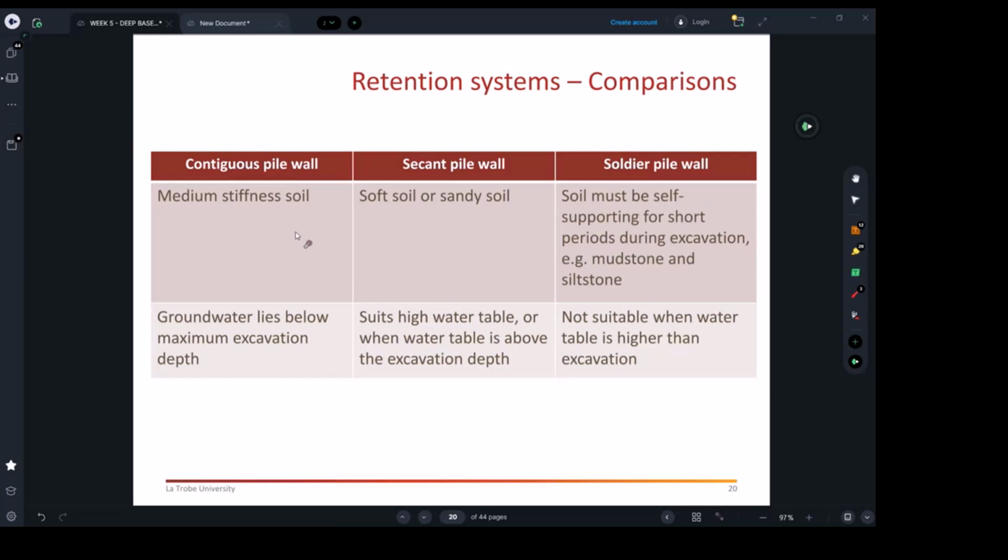Remember, when the soil engineer goes to inspect, they will take maybe 10 or 5 samples from different spots in the lot, but there is always a possibility that a corner of your site is different from the report. It may just not be the same condition. So who determines this? The builder, because they are on site and they know. You can't just follow the drawings and say that is what they said.